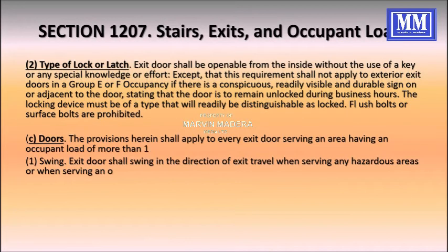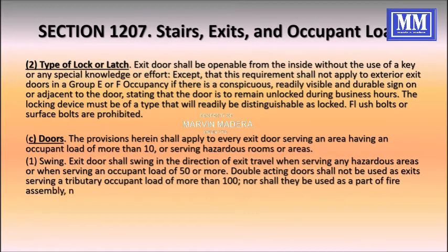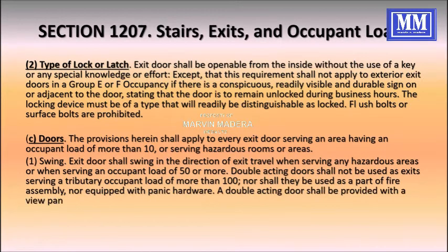Doors. The provisions herein shall apply to every exit door serving an area having an occupant load of more than 10 or serving hazardous rooms or areas. The swing of the exit doors: exit doors shall swing in the direction of the exit travel when serving any hazardous area or when serving an occupant load of 50 or more.